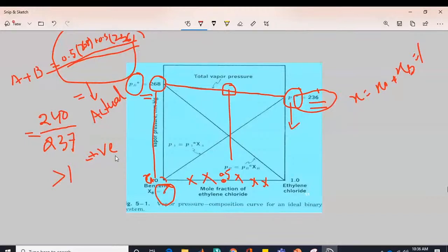Generally it is 180 if you're operating at atmospheric pressure, but if you're operating at vacuum, what do we do? We use pumps or compressors to get the air out of that system so that a vacuum is created, so there is no air pressure inside. So when the pressure is lower inside, the components inside this system will boil at low temperatures. This is how vacuum distillation works.